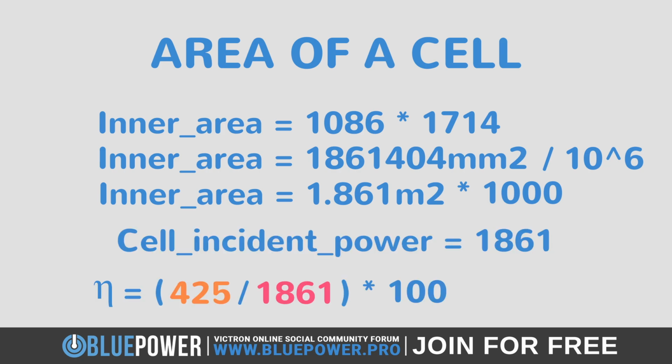Once done, we can then divide the total Pmax by this value, which, when multiplied by 100, results in a matching efficiency of 22.83%. So, while this is obviously not wildly greater than the total panel's efficiency of 21.27%, which includes the frame, it is slightly more accurate nonetheless. However, realistically, you won't see any real-world differences. But at least you now know how to calculate both.